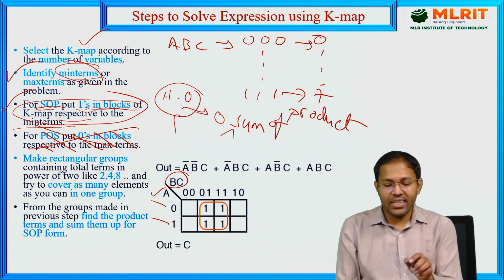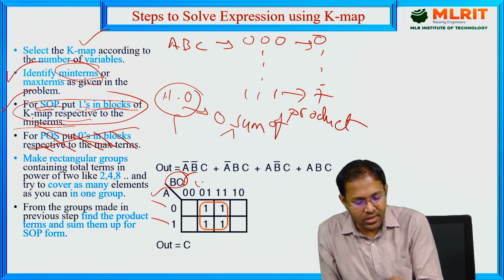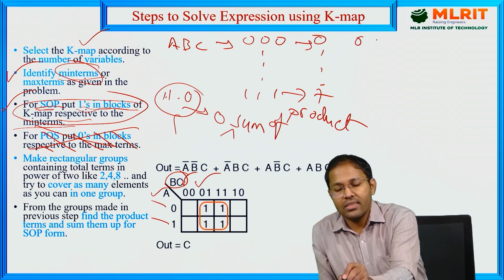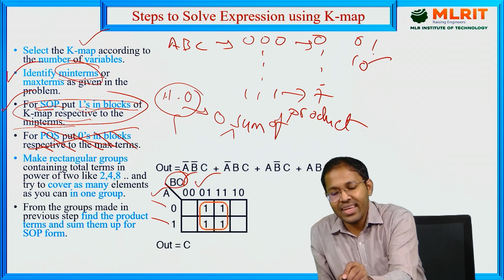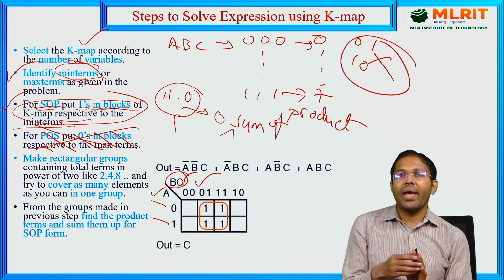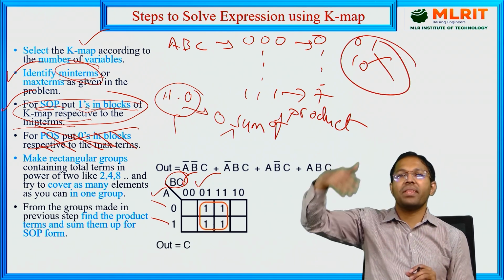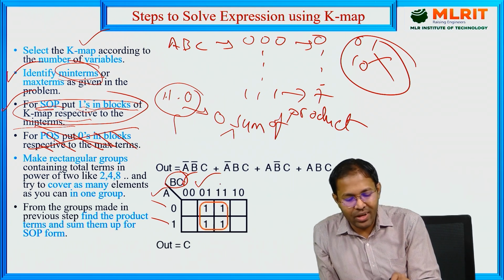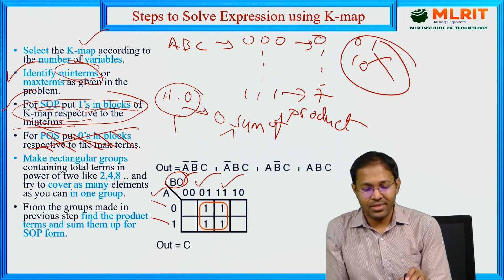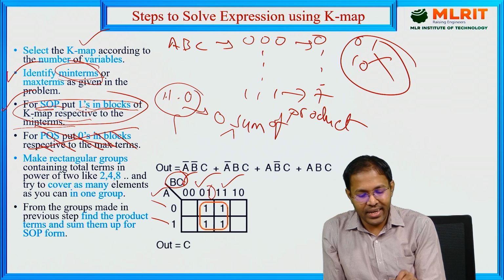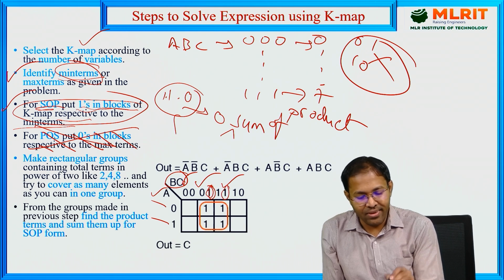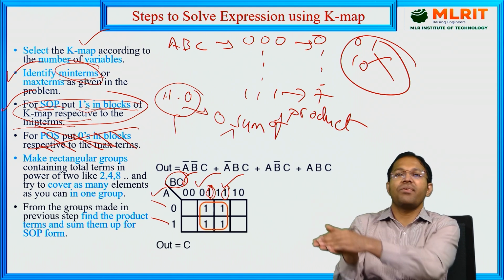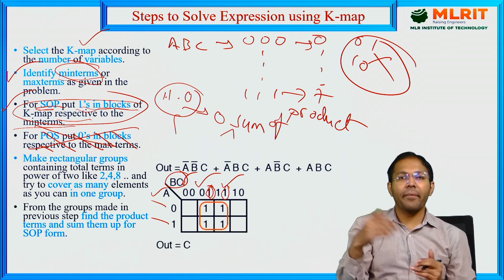So we will write 0, 0, 0, 1, but we should not write 1, 0 next, because in 0, 1 and 1, 0 nothing is common. K-map works by taking something in common. That is the reason after 0, 1 we are taking 1, 1, because the 1 here and this one both can be taken common and we could get a simplified expression by using K-map.